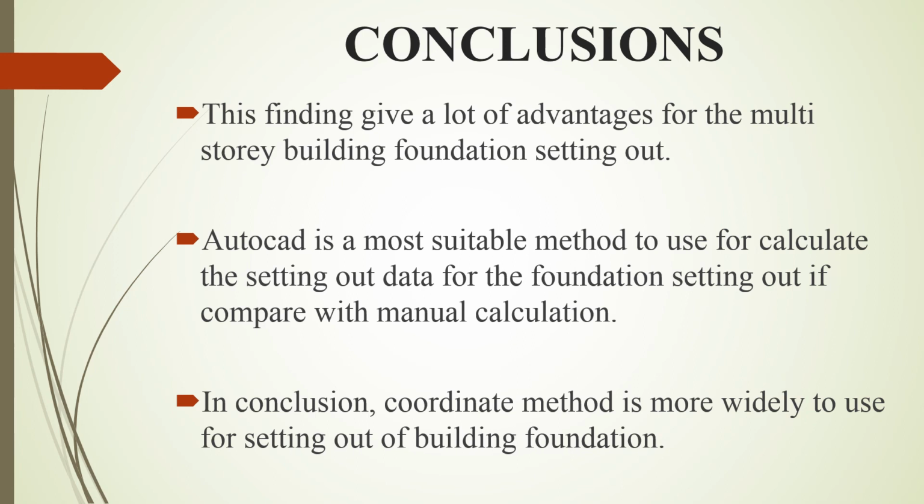AutoCAD is the most suitable method to use for calculating the setting out data for foundation setting out compared with manual calculation. The setting out data is almost the same in comparison between AutoCAD and manual calculation, but the AutoCAD method is easier, faster, and more accurate. In conclusion, the coordinate method is more widely used for setting out of building foundations.